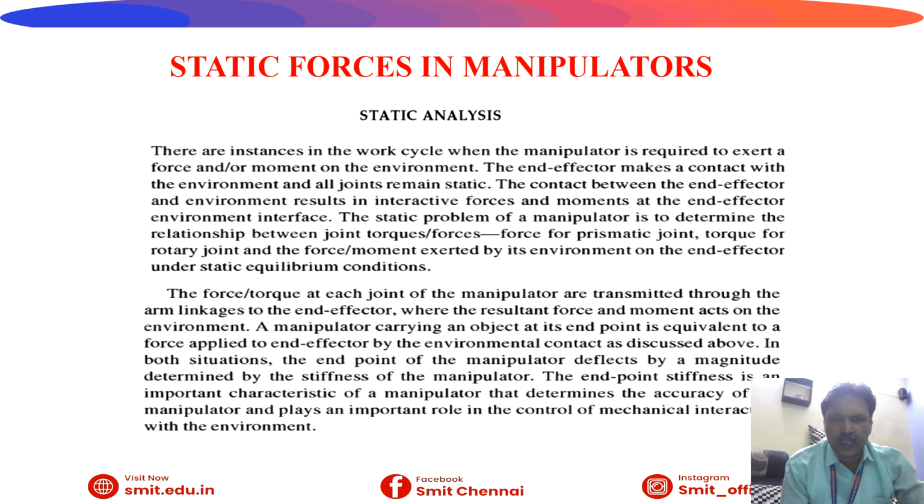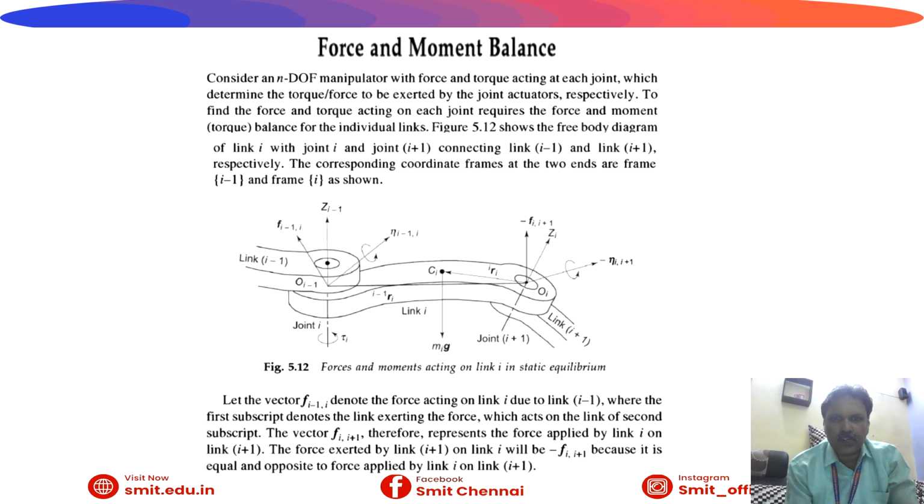In both situations, the end point of the manipulator deflects by a magnitude determined by the stiffness of the manipulator. Only by the stiffness of the manipulator can we determine that. Endpoint stiffness is an important characteristic of a manipulator that determines the accuracy of the manipulator and plays an important role in the control of mechanical interaction with the environment. In the upcoming slides we will see one by one about that.